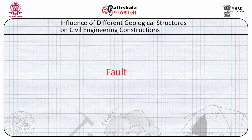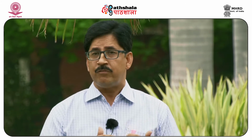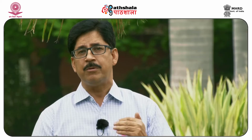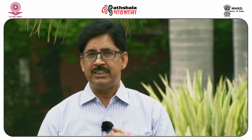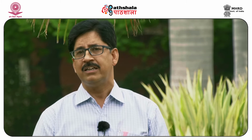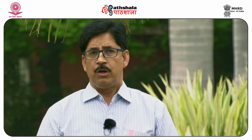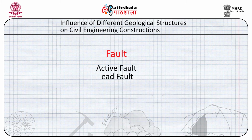Faults are not that common as compared to shear zones and joints, but if a fault is there, if your structure is of large length, for example tunnels may have very large length dimensions, then it may come across your tunnel. Similarly, if you have a dam having a very large axis length, then again the fault may come into your structure. We will try to first find out whether this fault is an active fault or a dead fault.